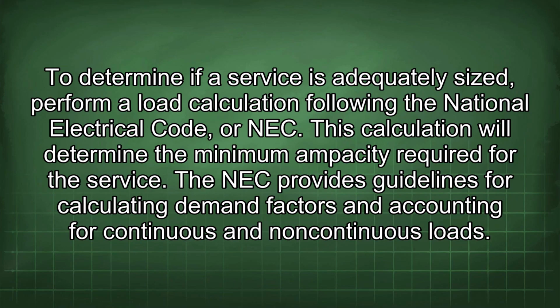To determine if a service is adequately sized, perform a load calculation following the National Electrical Code, or NEC. This calculation will determine the minimum ampacity required for the service. The NEC provides guidelines for calculating demand factors and accounting for continuous and non-continuous loads.